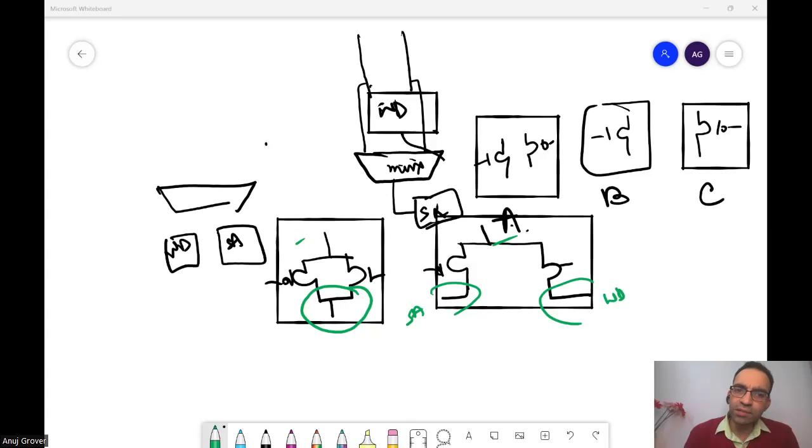In the first one, writing 0 may be easy, because there is an NMOS through which the write driver's signal will get transmitted to the bit line. Sir, is it due to the parasitic capacitance? Because here the junction capacitance is in parallel in the first case, and the effective capacitance increases, whereas in the second case it's not that way.